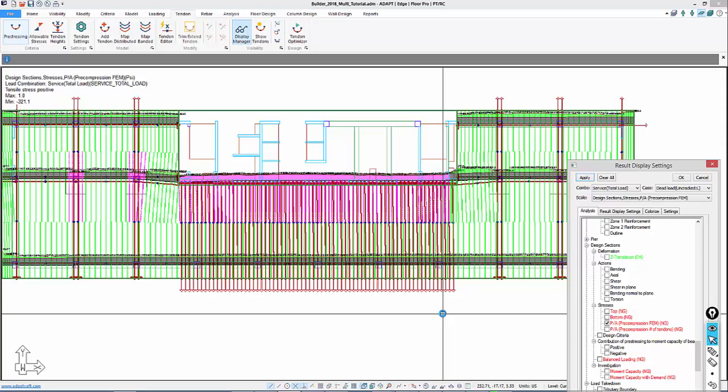So if you have fixed supports, if you have fixity between walls and slabs, this can affect the ability for the slab to shorten in plane in reality in the direction of the tendons. And whether or not that actually mimics real life condition based on your detailing depends on the outcome that was produced.